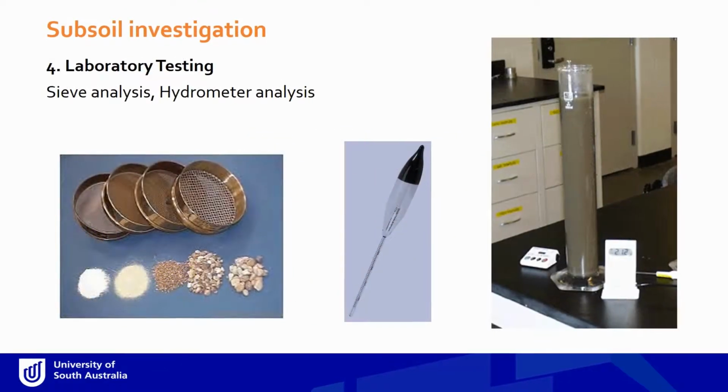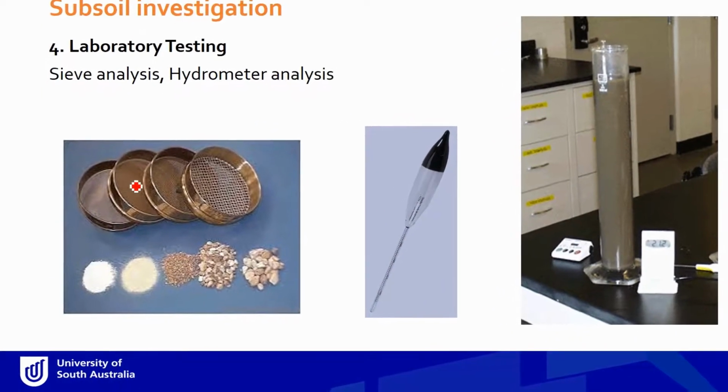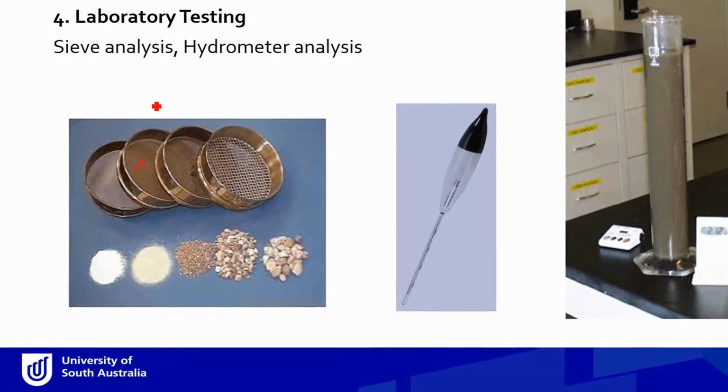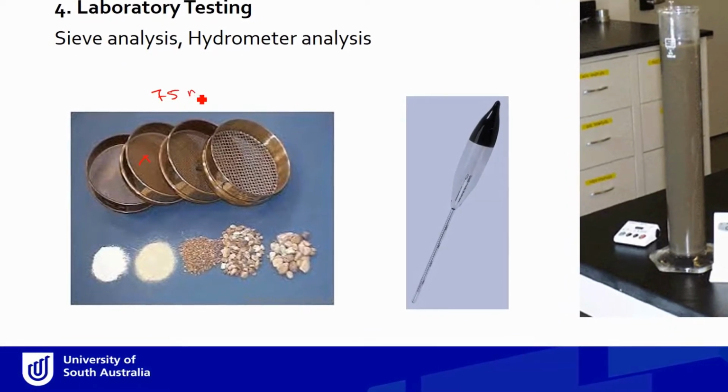Now for some soil, let's say the finest sieve, if this is the finest sieve, we have 75 micron. See in here, micron. So 75 micron is approximately a little less than a tenth of a millimeter, and anything finer than that, say soil particles, can be up to 2 micron, even smaller.